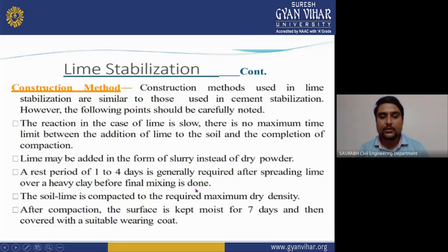A rest period of 1 to 4 days is generally required after spreading lime over heavy clay before the final mixing is done. The soil-lime is compacted to the required maximum dry density. After compaction, the surface is kept moist for 7 days and then covered with a suitable wearing coat.